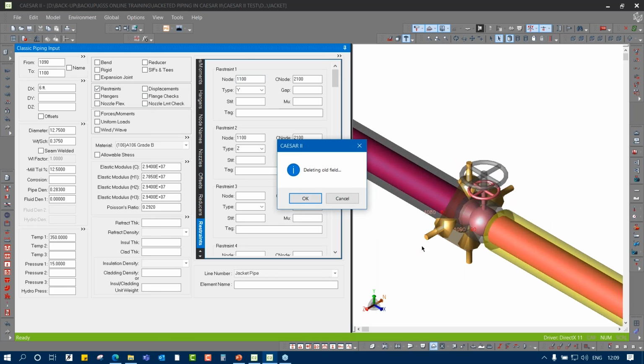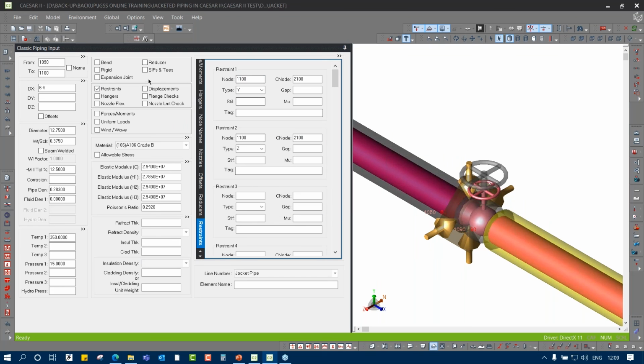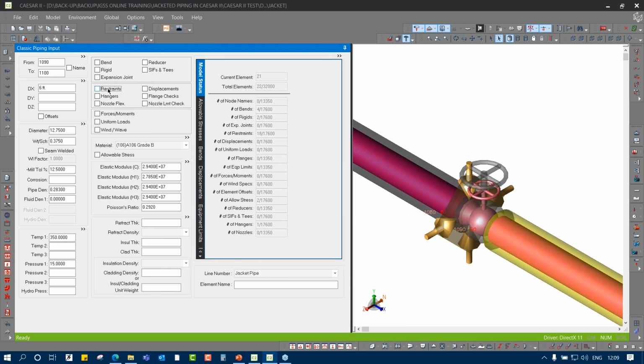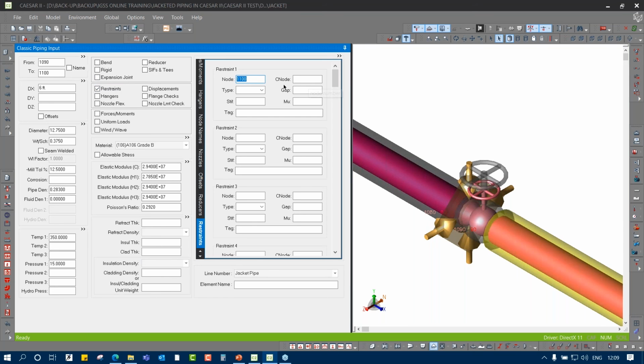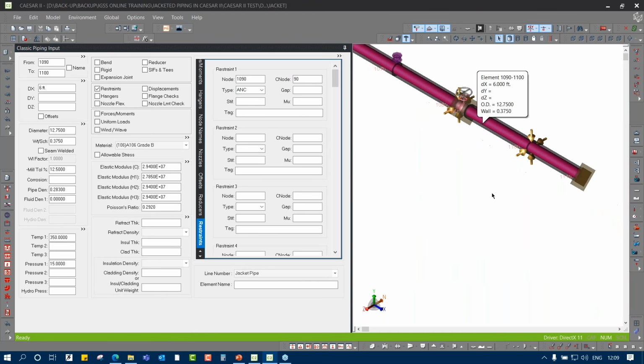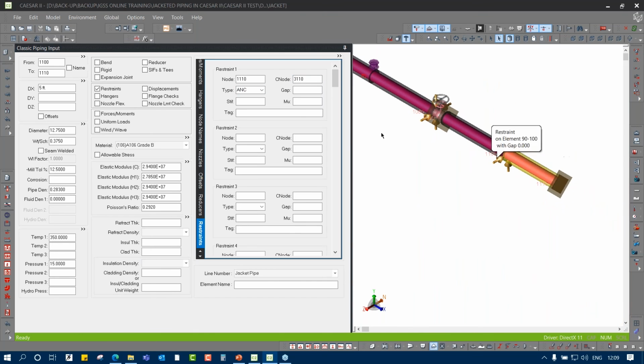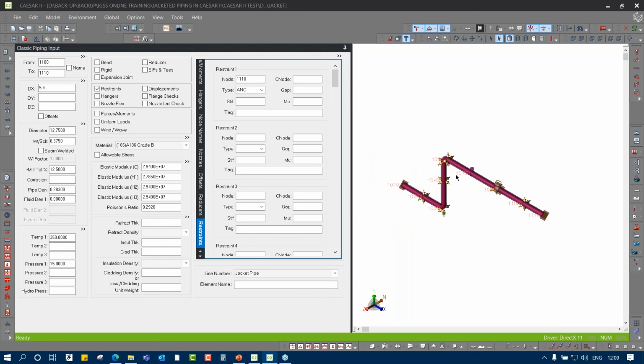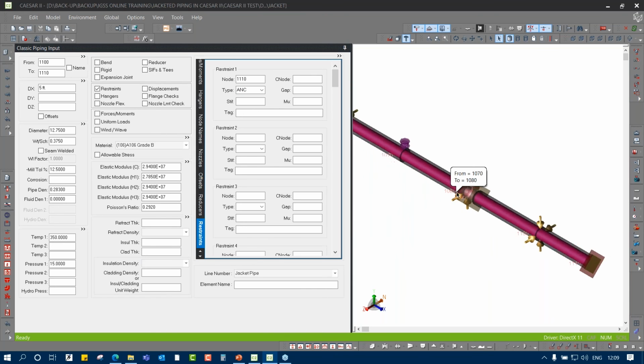Similarly, in this area, I don't want this support, but I want a special support at 1090, which is again on the core pipe, welded over the core pipe. And the last, only the core pipe. So this is the primary thing with respect to your jacket.